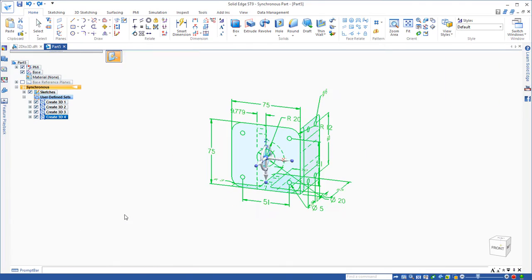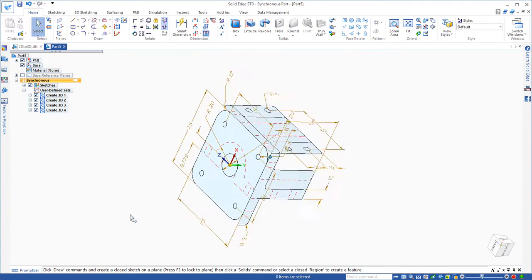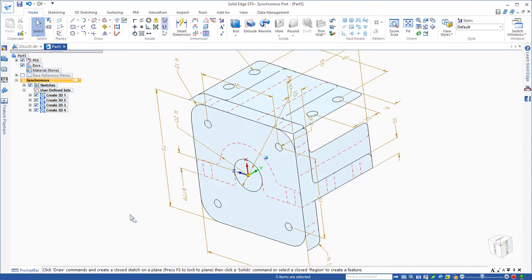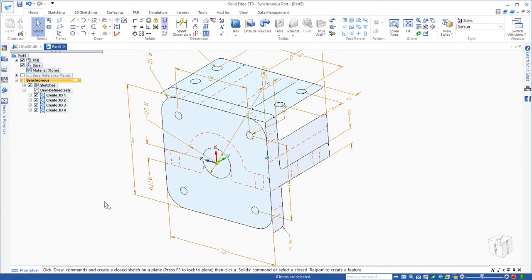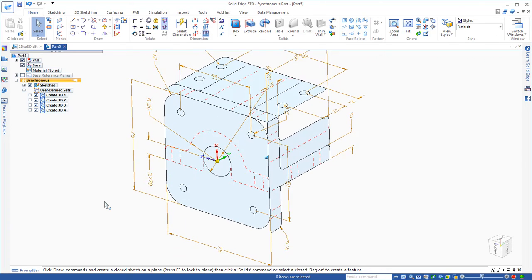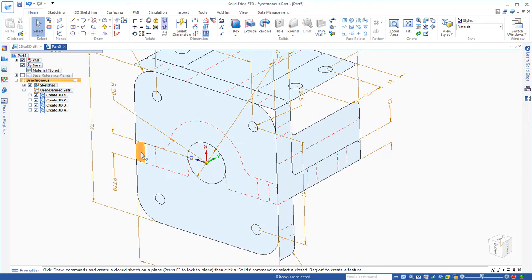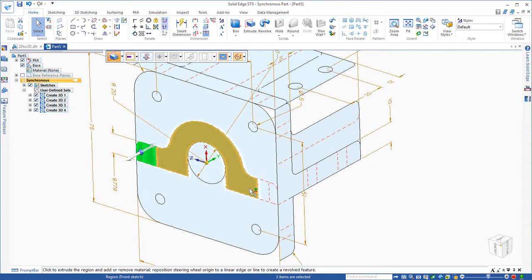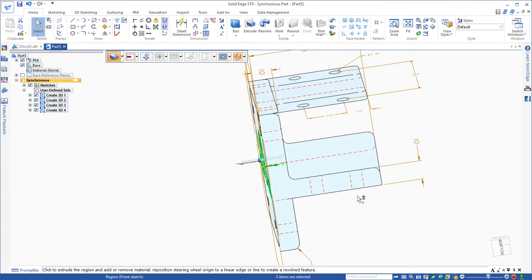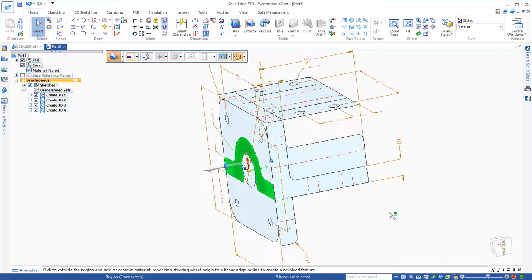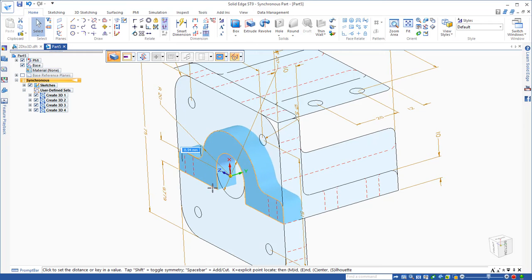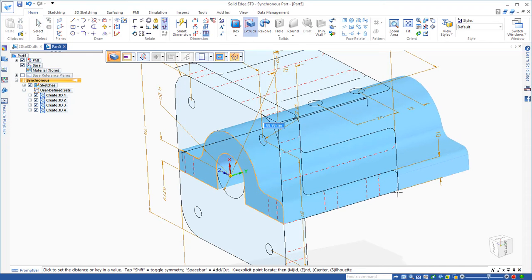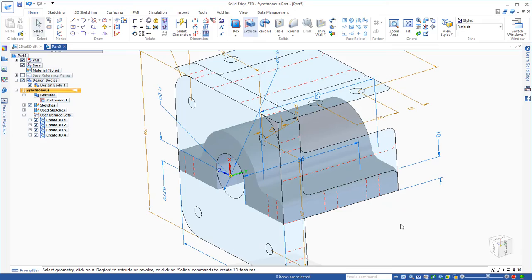And what that does is it aligns those views in the 3D space. So then we can take advantage of that geometry that's already been created, the manufacturing information from the DWG file, and begin to create a 3D model. So I'm just going to select the regions created by the intersecting sketches. First of all, for this particular shape, I can see that it's extruded all the way to the right based on the 2D drawing that has that view that's been aligned. So I'm just going to extrude, and I want to extrude right to that end point.